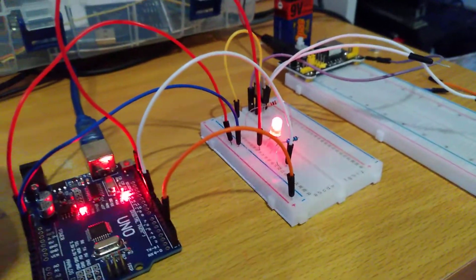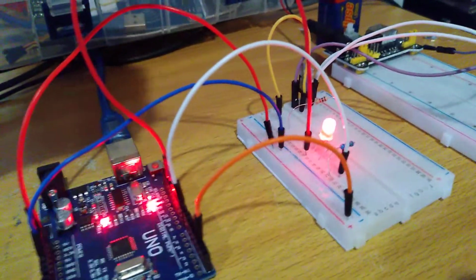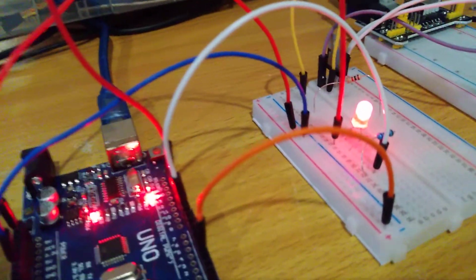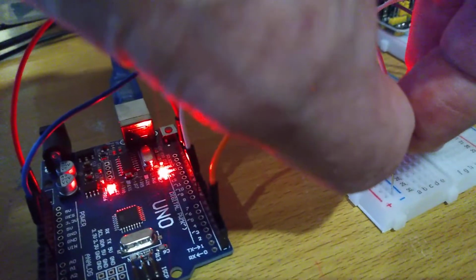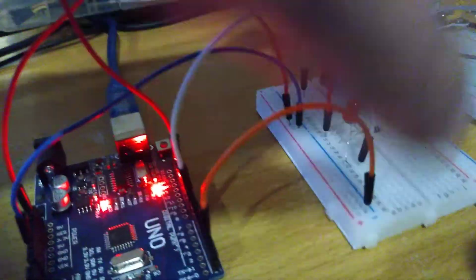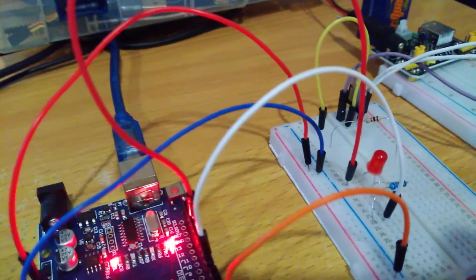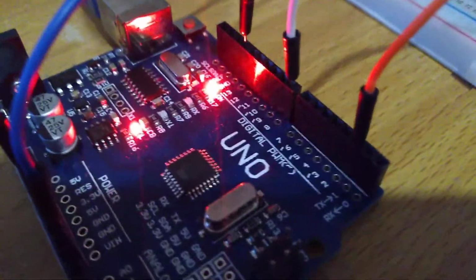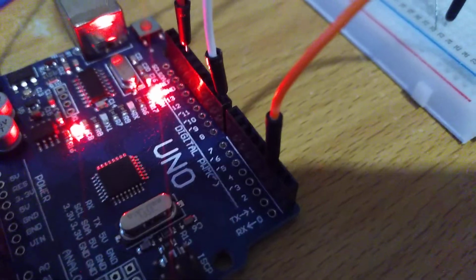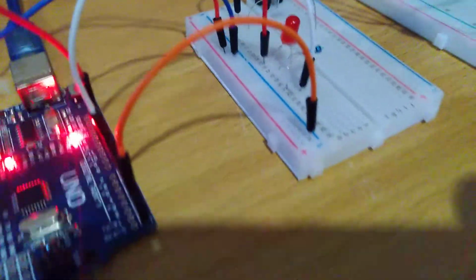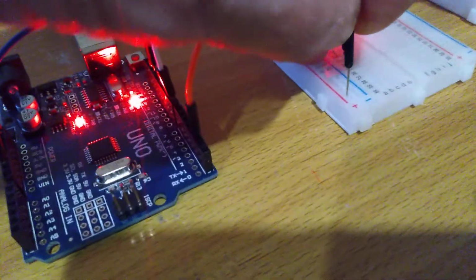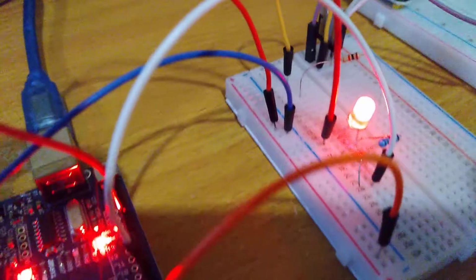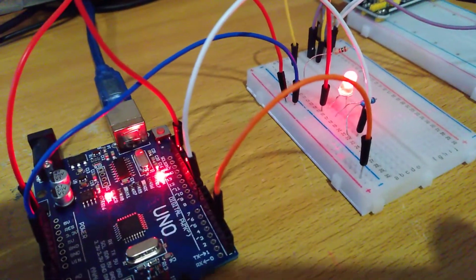Okay, I'll just demonstrate it running for a moment. At the moment my input is actually high on 5 volts and the LED is on. If I take it here to ground, you'll see my LED is now off. Now my pin 2, which is this pin down here, is actually at negative or ground. Down here I go back to my 5 volts positive again, and my LED is now high or on.